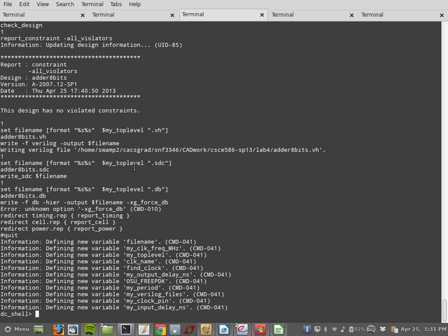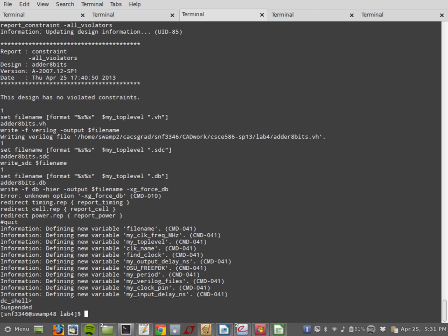And when it finishes, it gives you a bunch of other files other than the Verilog file, like reports, as in timing reports, power report, area report, all that stuff, which is very useful for you to put in the project report when you turn in your project later. You put the power report, the timing reports, all that information. So let's look at these reports.